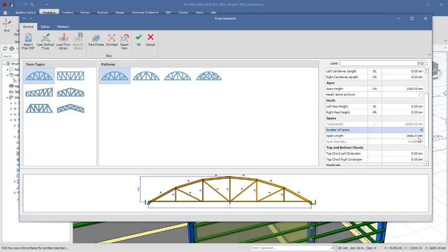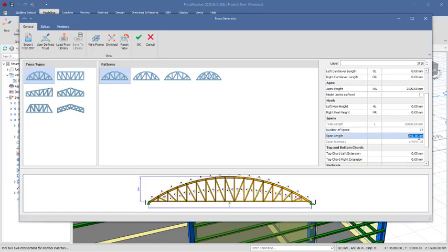So I will increase this to 18 right there. If I increase it to 18 and click in this provision, you see it has changed to 888.89. I don't want it to be less than 900 millimeters, so I will now key in 17 for that spacing right there. So I'm now having 941.18 millimeters right there. So I'm okay with this, all right. So these are the spacing of my purlins on the I section beam rafter, all right.